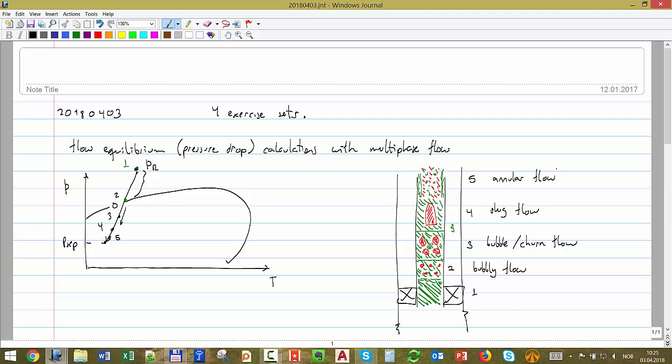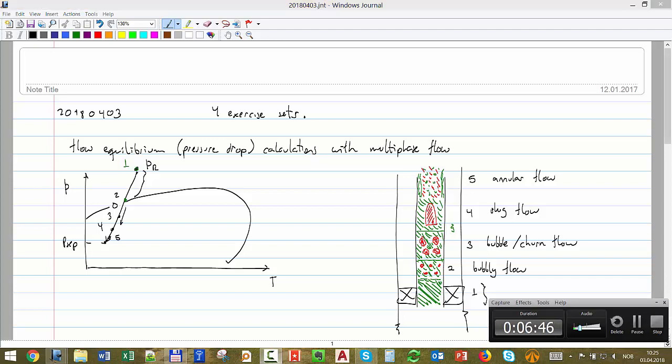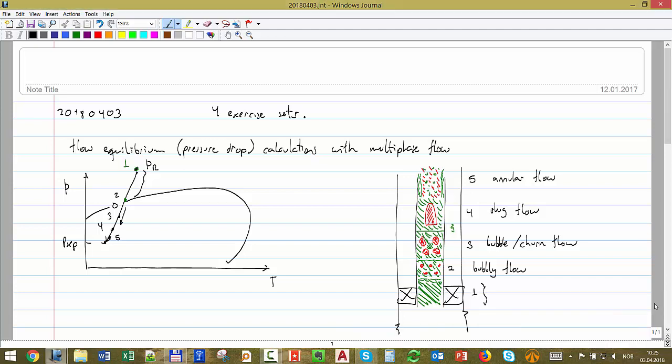And we can have all of them in one wellbore, and that's part of the complexity of performing multi-phase calculations. Before we were saying, well, the only thing I have to change is the rate, right? But now along the conduit where you want to make your calculations, you will have different flow patterns, different distributions of how the flow is arranged.